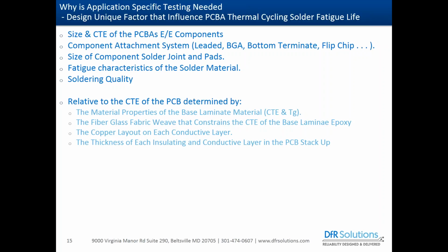All of those have highly different durability life characteristics that we'll be showing here. The size of the component and the size of its solder joints and pads. The fatigue characteristics of the solder material that's being used. We know that today's lead-free solders take higher temperatures and will take more thermal stress than the old tin-lead solders we used to use.